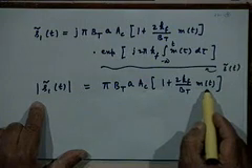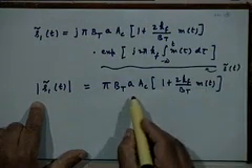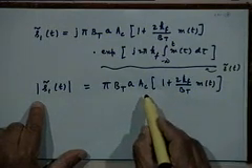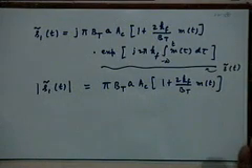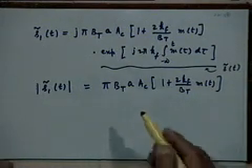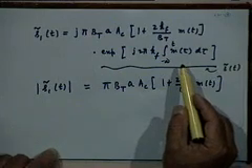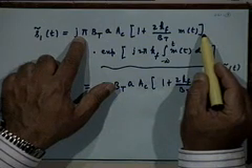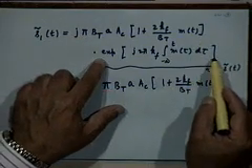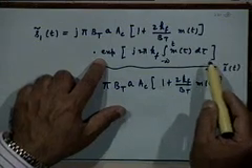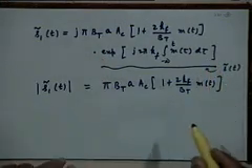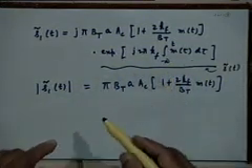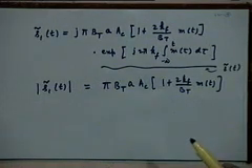with the problem that we have already discussed, that there is a DC component which we did not want. It is the same thing we argued physically earlier: this slope circuit converts the FM signal, or the angle modulated signal, into an amplitude modulated signal. This represents the amplitude modulation, and this represents the carrier. The only thing is, in this case the carrier is not of constant frequency, but is itself an FM modulated carrier.